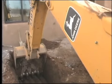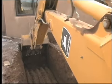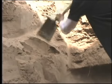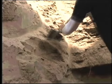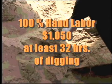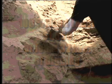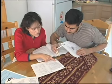In 2001, the cost of having a conventional septic tank and chamber drain field installed by a certified installer in New Mexico ranged in price from $1,700 to $2,600, and the installer usually filed the permit application. The cost of installing a septic tank and chamber drain field using 100% hand labor is about $1,050, and you can expect to spend at least 32 hours digging for a typical system. In addition, you will be responsible for the system design and filing the permit paperwork.